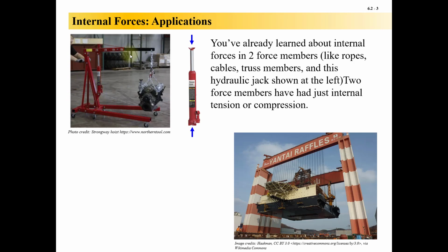You can see this engine hoist. We talked about this in a previous lesson. It has this black boom here that extends out from this red arm, so it can go further out. And along the red arm here, I think they have some load capacities. The farther out this goes, the lower the load capacity of this crane. It can pick up a lighter and lighter engine. And that's because of the internal forces that are occurring inside this member and inside the black extension piece, as well as inside of the other components.